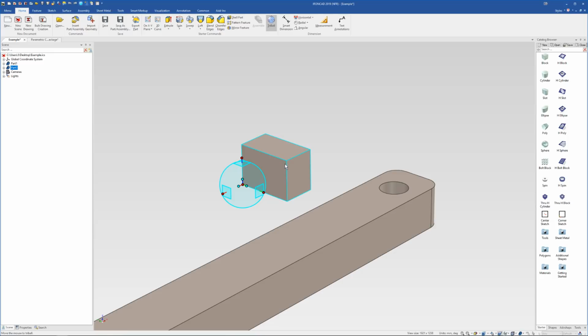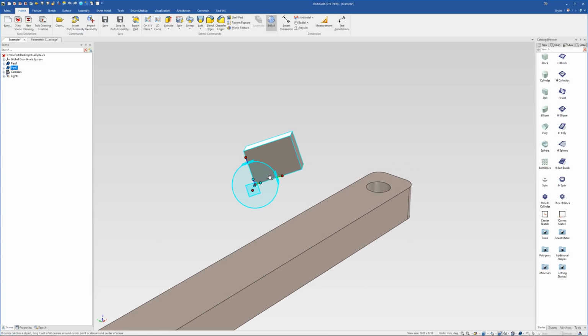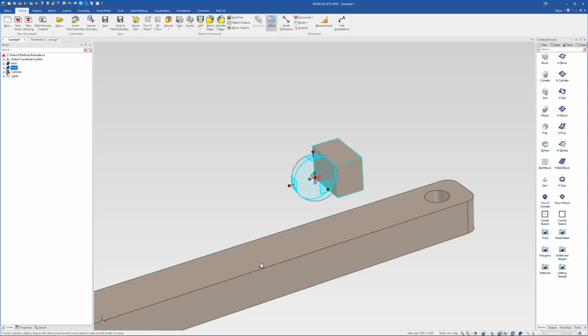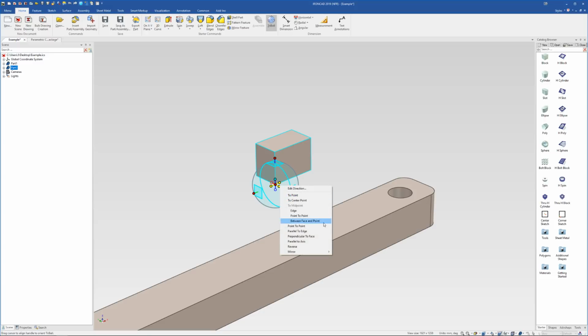So if we just go back here a step, so we are in that location there, what we can also do is just hold down this handle, click and drag on this handle, and I can just go snap to that face, snap to this face, and then we're done. So basically, when you drag that handle over a face, you're snapping to perpendicular with that face. And if you drag that handle to an edge, you're snapping to aligning to that edge. So it's doing the same thing as the right clicking and choosing an option.